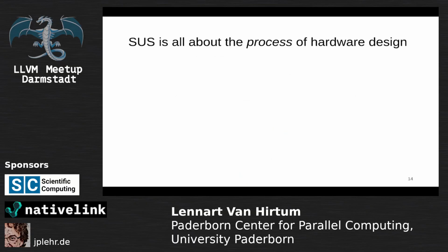So SUS is all about the process of hardware design. It is to make it possible to do little tweaks, to improve your code, to move things around without much mental overhead. Of course, being a proper hardware design language, we need to have full control. So this will highly limit what kind of abstractions we can create. The philosophy in SUS is if you can draw it, you can write it in SUS. So that means we can only provide tools to deal with the complexity, to have the compiler think with you, but we can never have the compiler think for you.